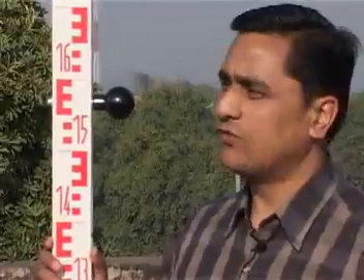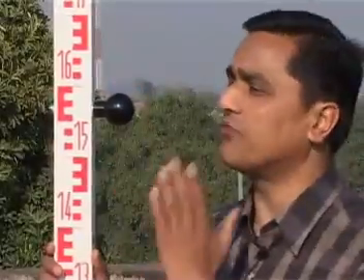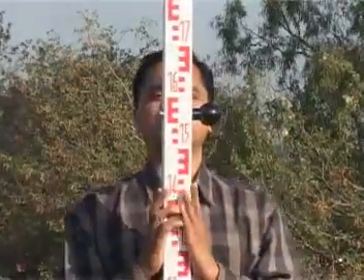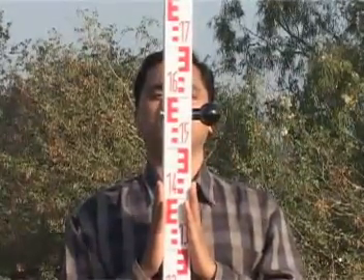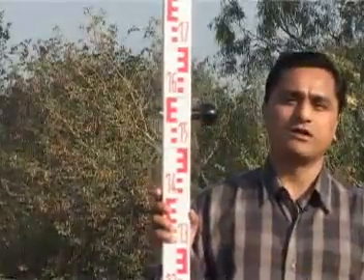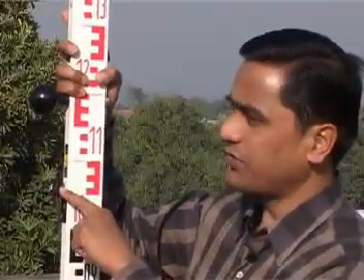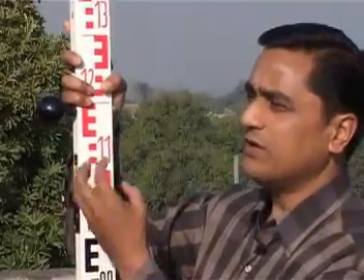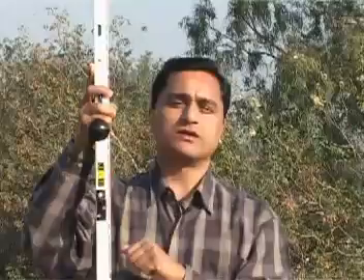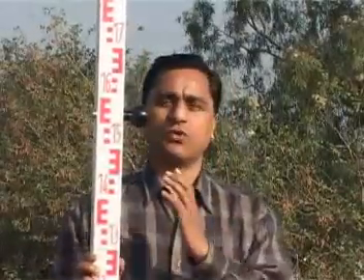Now how to work with this? When you are holding it, the staff should be vertical, obviously. In order to make it vertical, generally we hold the staff in this position, standing vertical. So right now the staff is vertical. In order to ensure that the staff is really vertical, we can make use of a bubble tube. Over here you can see we have a bubble tube, a circular bubble. So I try to make the circular bubble in center. Once the circular bubble is in center, our staff will be vertical. So this is important, how we hold it, and we should hold it vertically.